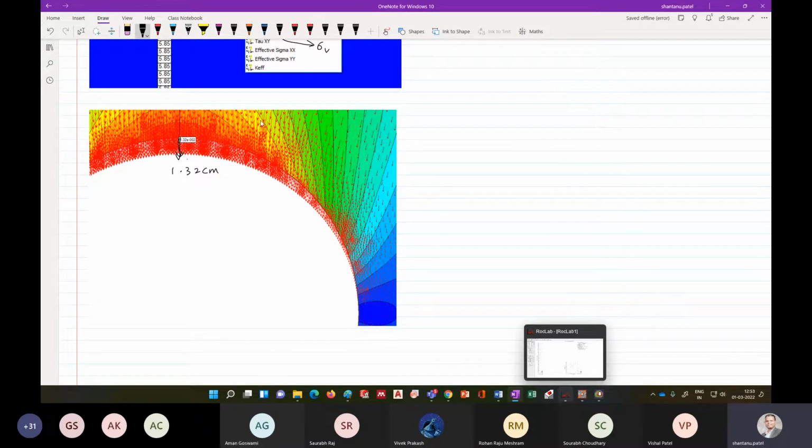And the arrows are saying what the displacement is at each point. Because we applied 19.5 from the top and 5.85 from the side, we expect that because this stress is more, this point will displace more, right? And this is exactly what it is doing. And this point has almost zero displacement. Okay, is this clear? So these are the displacement contours.